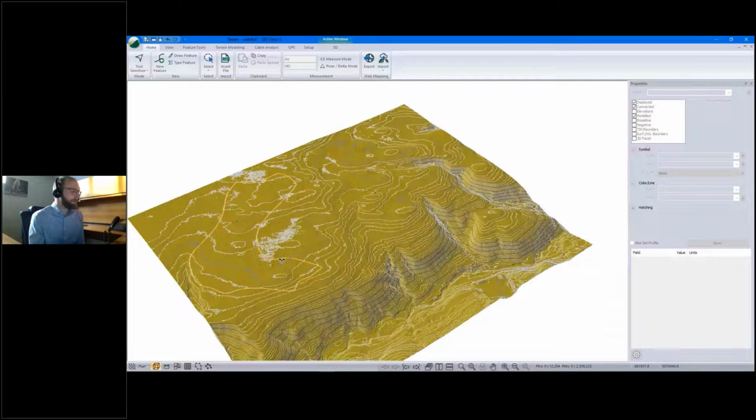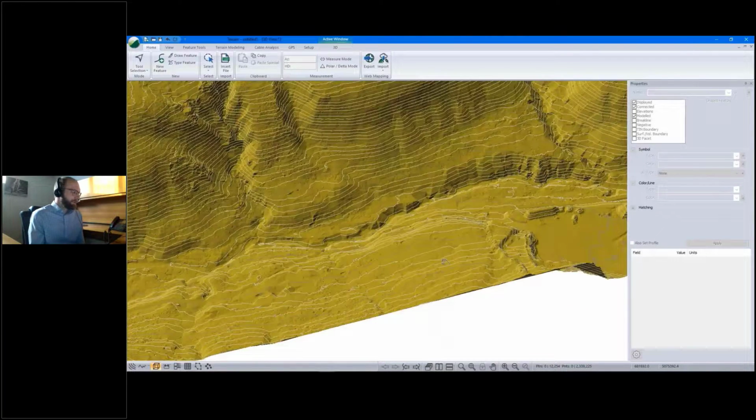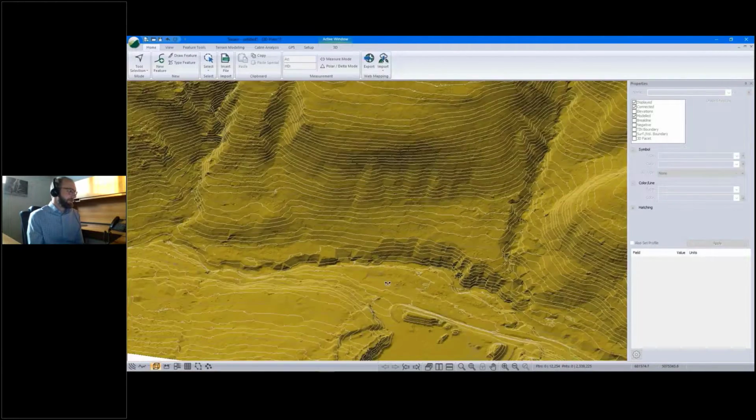And when I'm checking that, I'm going to start out just kind of at a landscape level, look for any obvious issues. I'm also going to start to look for any landscape features that may give me an indication of hazards or what geotechnical conditions to expect. And I'm going to begin to piece together where I might have an opportunity to get a road.